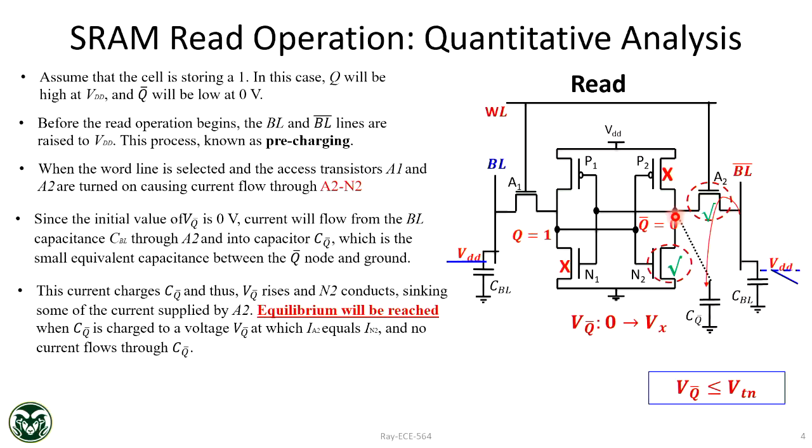And for the sense amplifier to sense, you need some voltage difference. This is always kept at VDD, say 1 volt. This has to go down to, say, 0.8 volt or 0.9 volt, so that the sense amplifier will amplify this 100 millivolt delta. If it is only, say, a 50 millivolt delta, then the sense amplifier will not be able to do that.